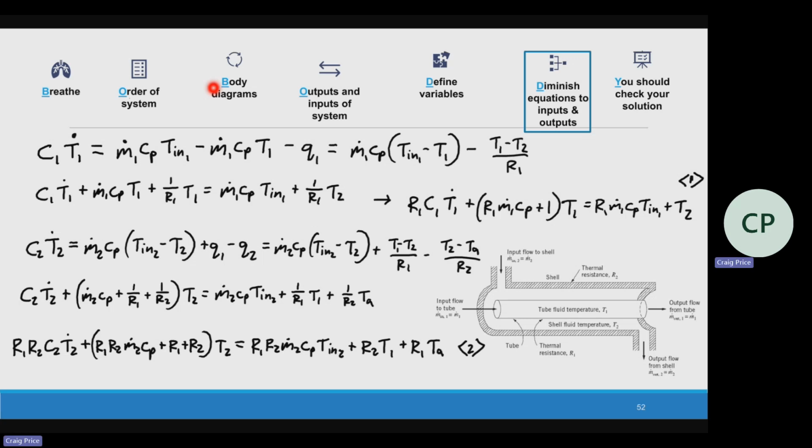Again, the process is very similar to hydraulics. I have a capacitance, therefore I have a first order equation. You identify what is the input flow, output flow. Just like with that one, that's C P dot, how the pressure is changing. This one is capacitance times temperature dot. How's the temperature changing? So just using that equation sheet, you don't have to memorize anything. It's just identifying inputs, outputs, following your diagram, and then getting one. And it should always be stable. The output side should be stable, like both of these are, which means all positive on the output side.